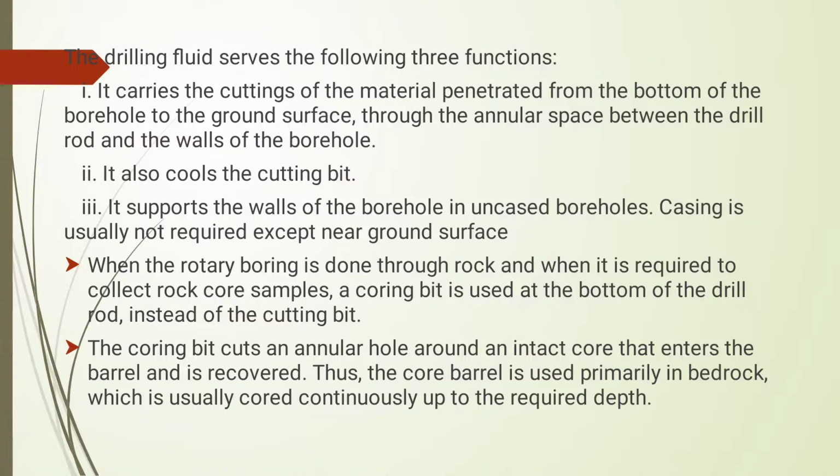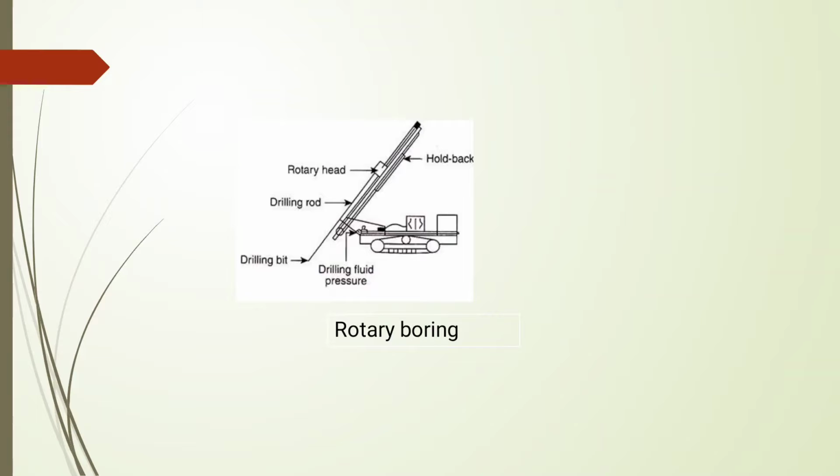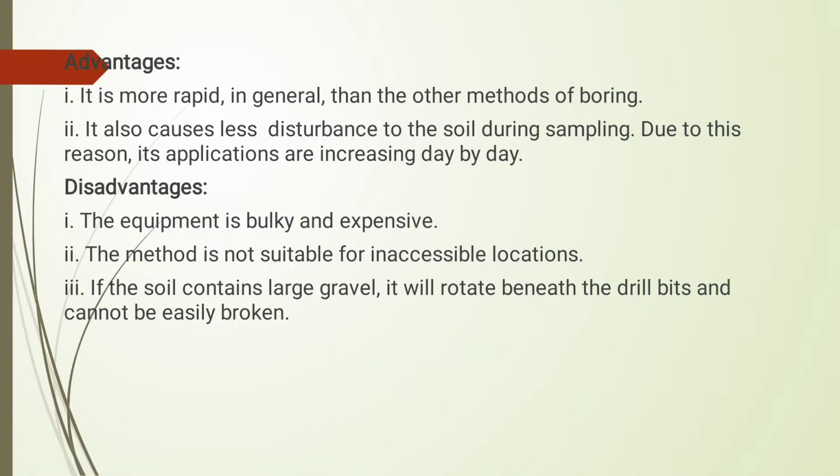When the rotary boring is done through rock and it is required to collect a rock core sample, a coring bit is attached at the bottom of the drill rod instead of the cutting bit. So this is a figure for rotary boring. Next, the advantages of rotary boring.